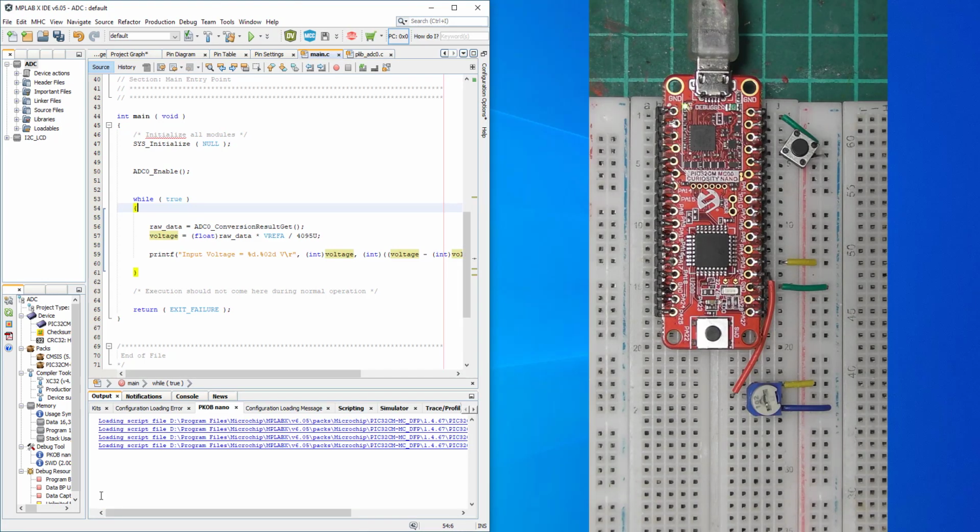Let's have a look at the hardware connections. On our board, what we can see is we've got our pot that is feeding the analog value into the pin number PA2 on the board. We have our voltage reference 5 volts from here, which is taken from this pin on our nano board, and this is just a reset switch. So not much to this. Let's have a look. Maybe first I'll try to connect the multimeter, so we will check our reference voltage.